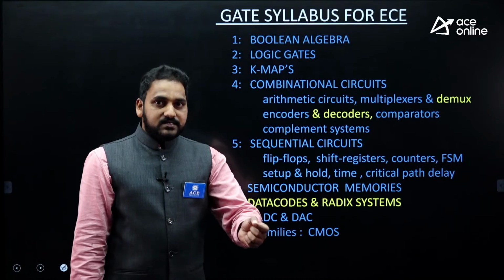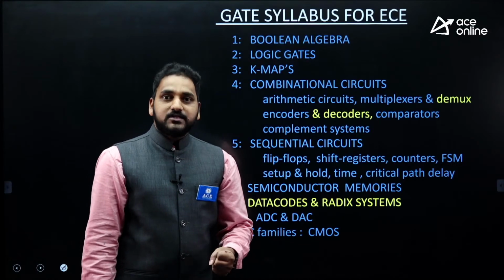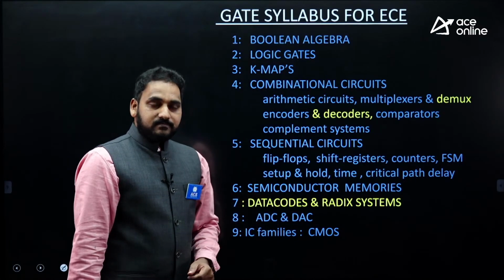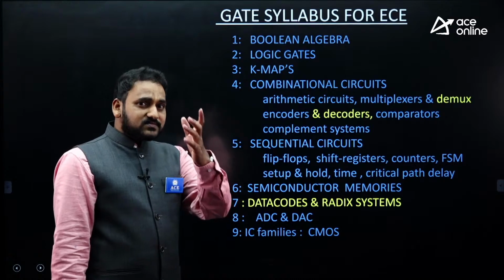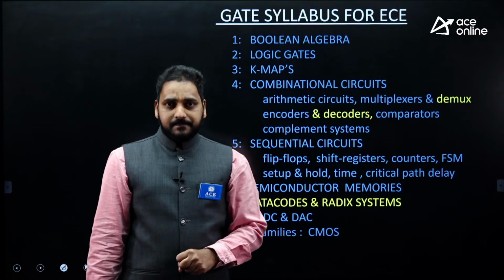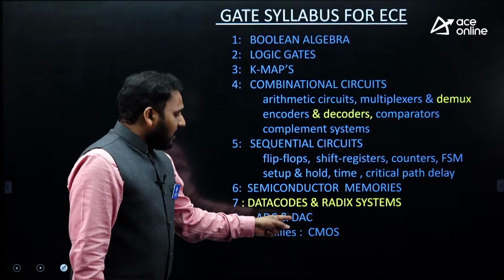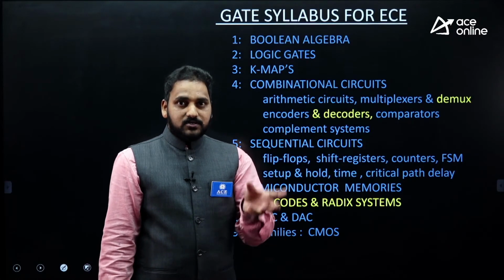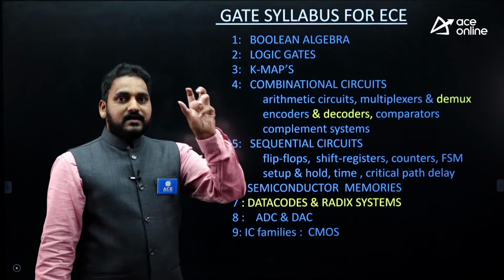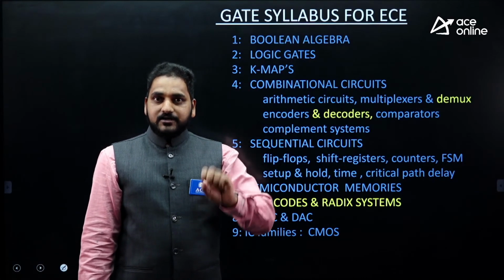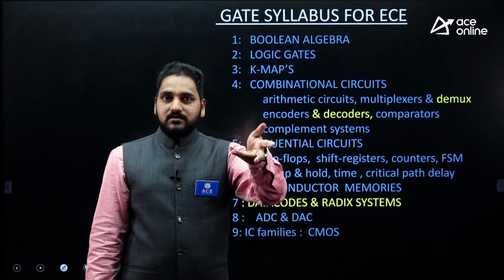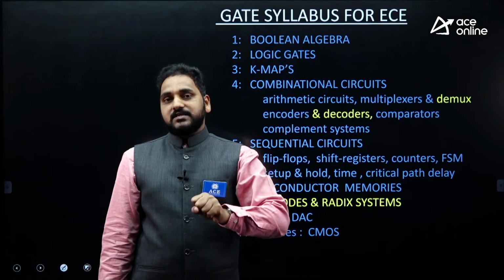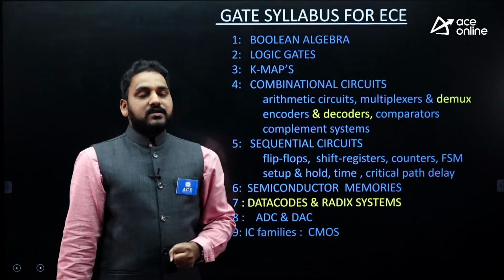Strictly speaking, Thevenin's and superposition, these theorems have to be used by the student to analyze the digital to analog converters, and especially the R to 2R ladder network type. In R to 2R ladder network, there are 2 types, voltage switching type and current switching type. Both completely look like an analog circuit. And to analyze it, students should be good in operational amplifiers as well as resistive circuit design. It is a fundamental from your network theory.